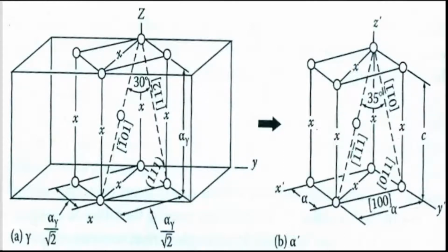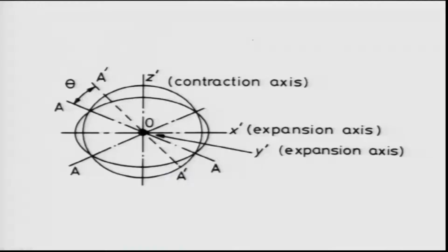Similarly, some crystallographic directions also will be parallel to each other. So depending on the type of steel, people have observed different orientation relationships, and that is, crystallographically they are related. So those plates which you see are actually not completely invariant with respect to the austenite. They have a distinct crystallographic relationship with the austenite, and that's obviously understandable from the way the transformation occurs.